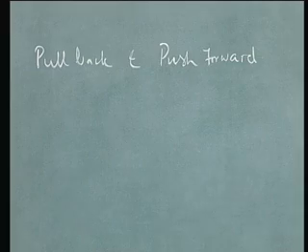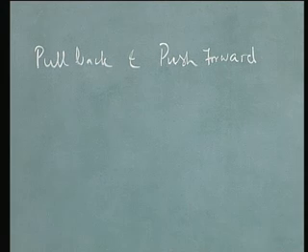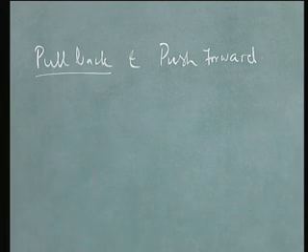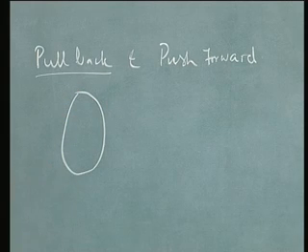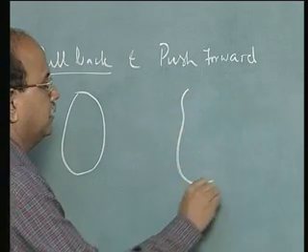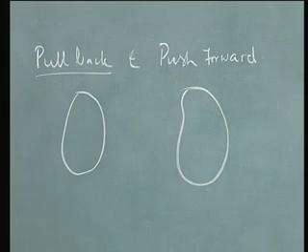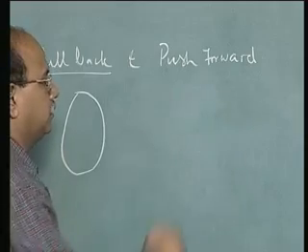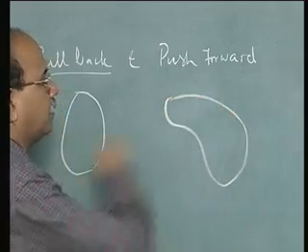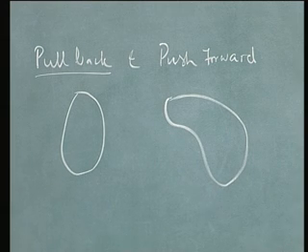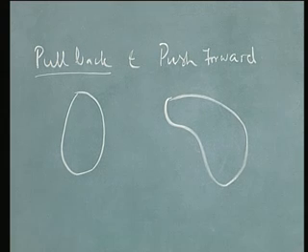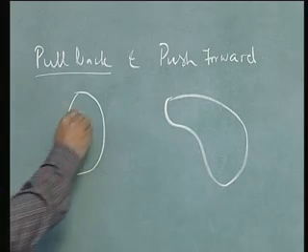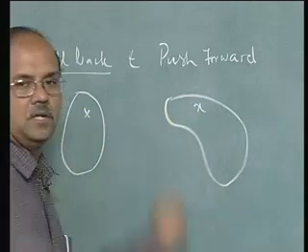So let us look at what is pullback and push forward. What do you understand by the term, say, pullback? The setting is something like this. I have now the body at a reference configuration, and that body is deformed. Let me really deform the body, so that body might have really deformed. Now there is definitely a pullback and push forward that is possible between these two configurations. The capital X belongs to this, small x belongs to this, and so on.